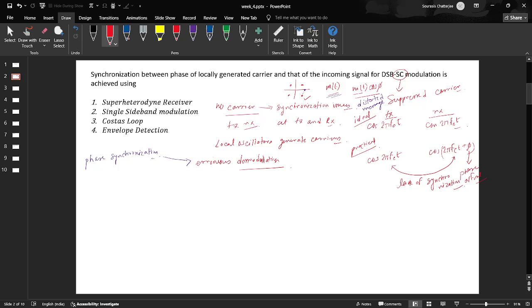You need to fix that. Since it's DSBSC, we cannot really go back to ordinary AM where we transmit the carrier, spending a huge power behind it, which is essentially transmitting no information. So in the absence of a carrier, at the receiver end you just need a simple circuit. Instead of getting into the math first, let me draw the circuit and how it behaves. That would help you better visualize how this phase synchronization matter can be handled at the receiver end.